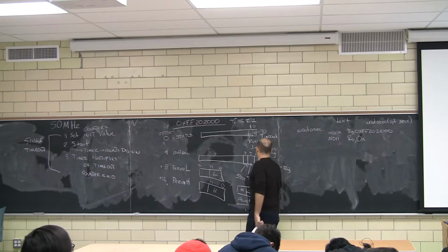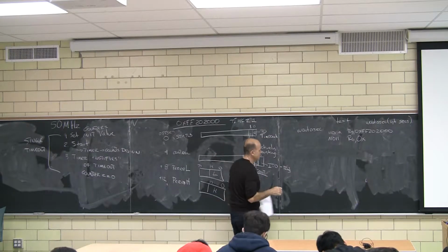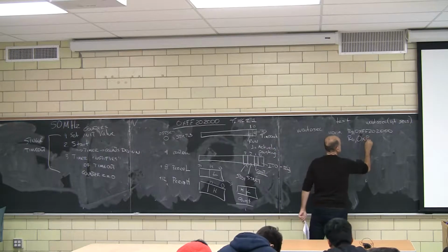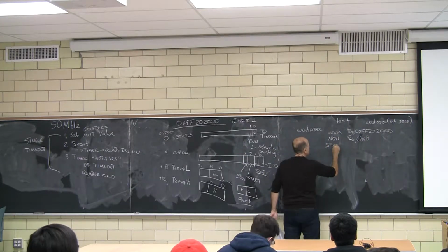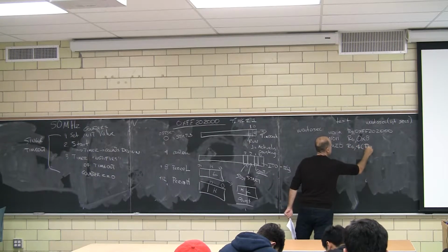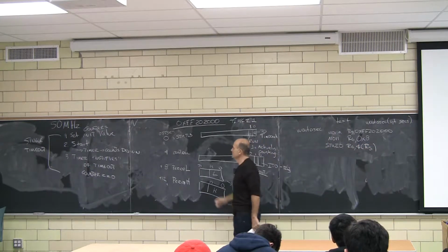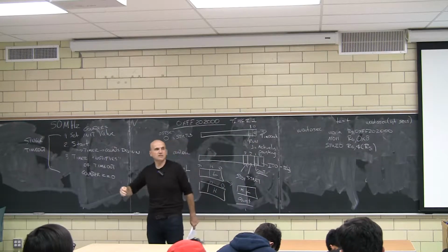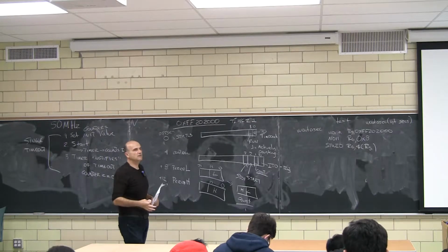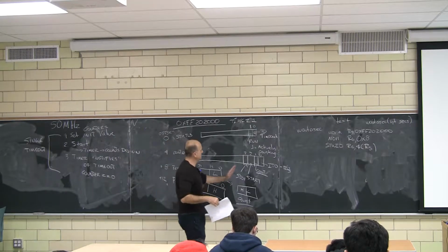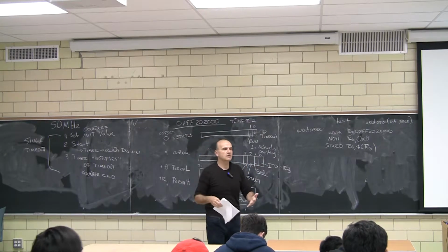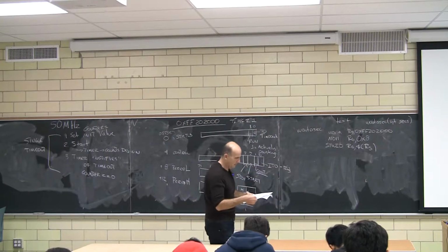So 1, 2, 4, 8, right? Store word IO R6 4 R5. Okay, what does that mean? The control register is a distance plus 4 from the base of the device. We're going there and we're writing a value that has only 1 bit set, and that happens to be at this position. Everything else is set to 0. What does this thing do? It resets the timer.